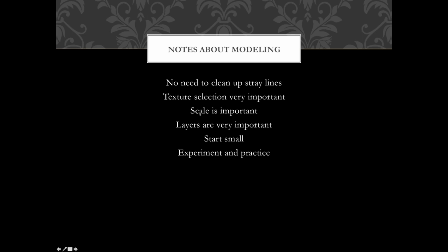And since you're basically simulating how light actually is hitting things, scale is important. So it's important to build your things at how big they actually are in real life. I know some people in the SketchUp libraries build their models 2-3 times scale just to make it easier as they model, but it does weird things if you try and render those. So that's something to watch out for.